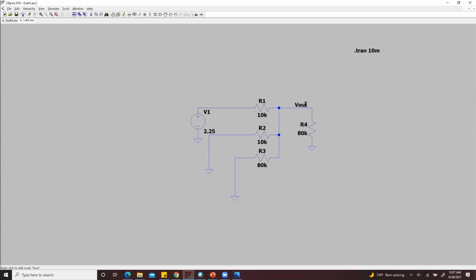That will be your Vout1. Then you do the same thing: short V1, short V3, and treat V2 as your only input, and you simulate Vout2. Then V3, and then the final Vout when all 3 voltage sources are turned on together.